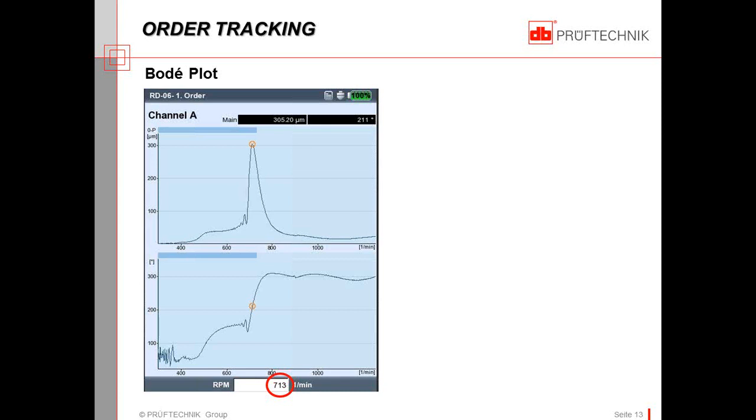In the illustration here, I have amplitude, and this is a measurement that I made a year or two ago. Basically, the machine was running up at 3,000, 3,500 RPM, and I started the measurement around 3,000 RPM. I've got that cut off here now, but we tracked the 1x vibration all the way down to slow roll. But when it got to around 700 RPM, there was a peak, and then it dropped off quickly through to slow roll. Again, that's amplitude versus RPM.